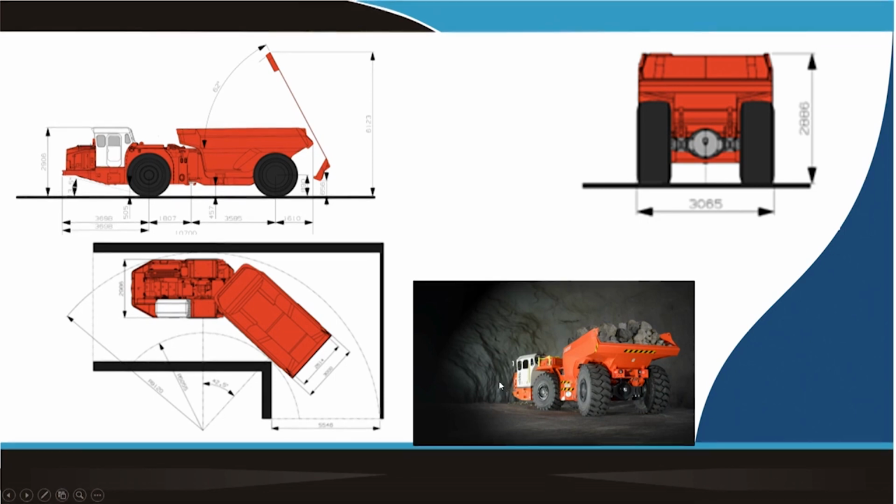It may so happen that a certain machine, in spite of matching your capacity, cannot be selected because of the dimensional conditions. So, you should always refer to the leaflets or the design specifications given by the machine manufacturers and see whether these are compatible under your operating conditions or not.